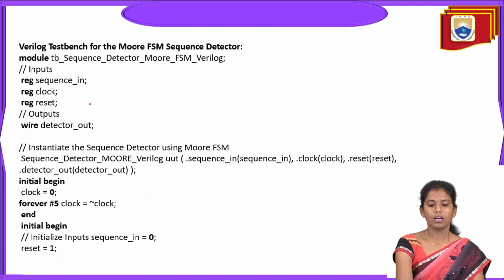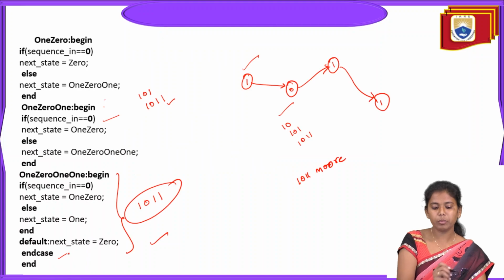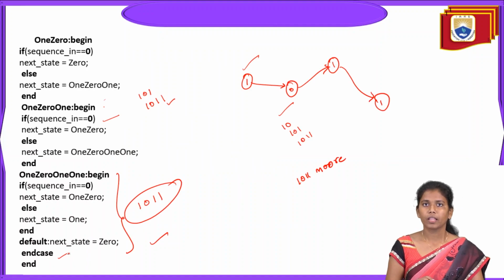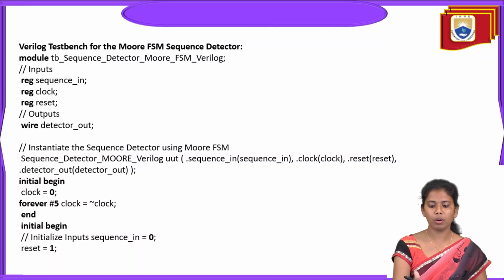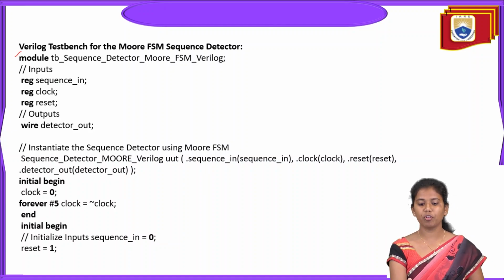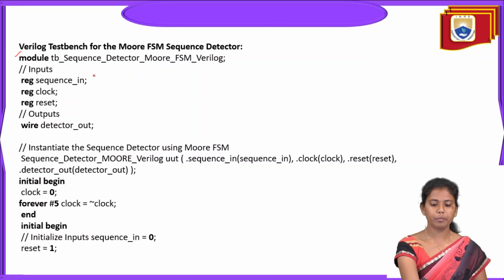So after this, this is what finally we are terminating with this end module. Then after writing the Verilog code, soon after you have to write the test bench code as well. In the test bench code, we simply mention the module instantiation of the module, then the instance name followed with the port list.